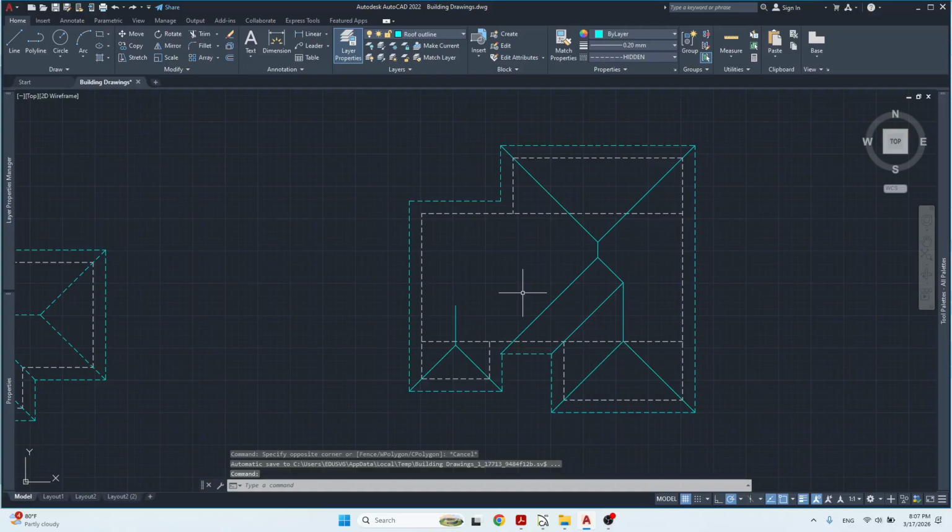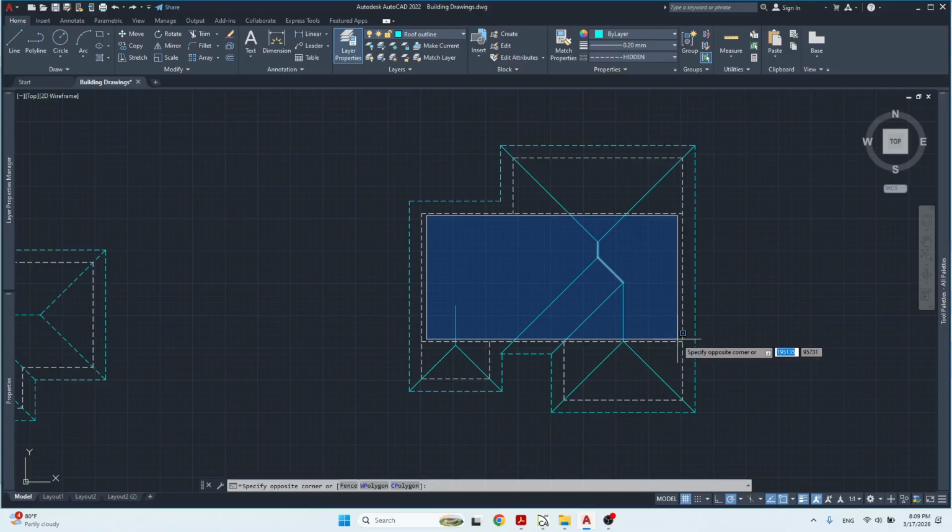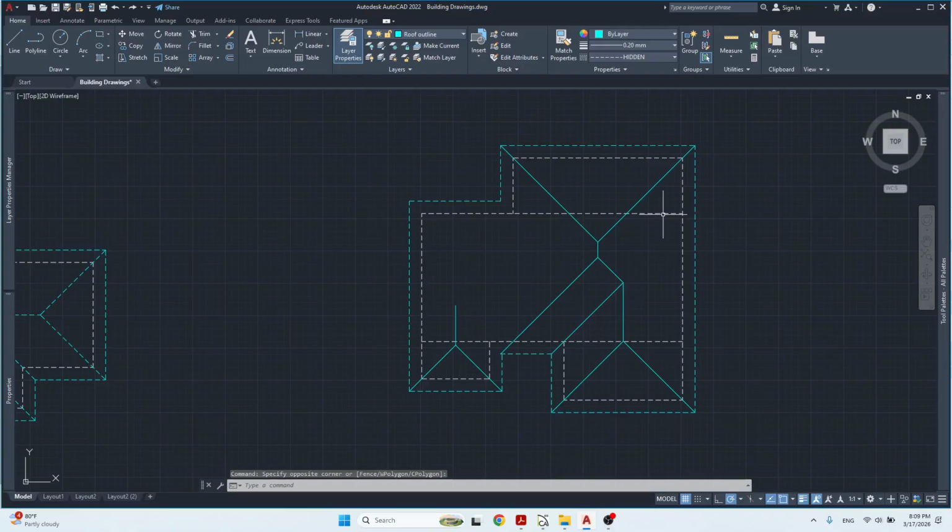Okay, so if you're treating this as its own section, that means you would have to draw our hip lines over here. But since this side is already completed, we don't need to worry about doing anything over here, right? We can just worry about this side. So let's look at this side of this rectangle here as its own building, with its own roof.